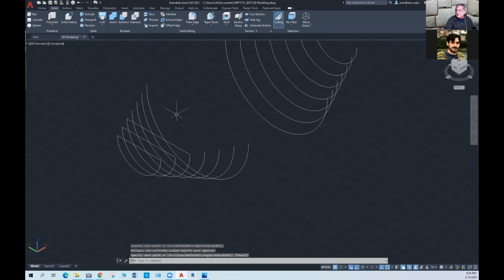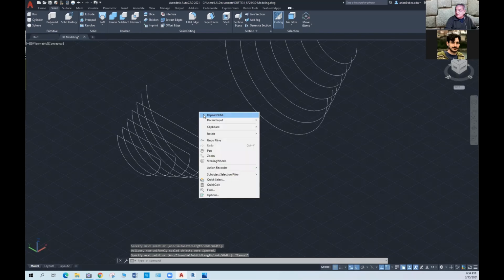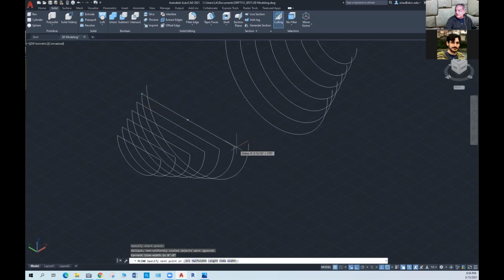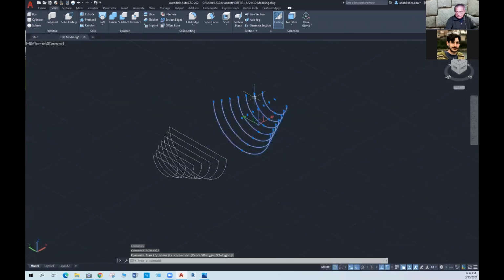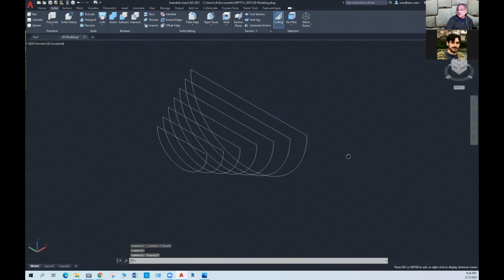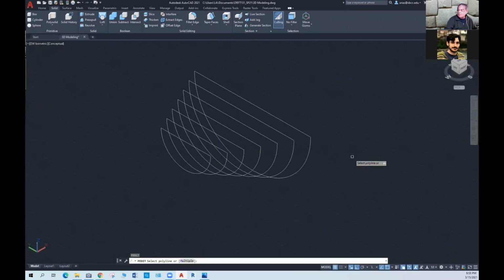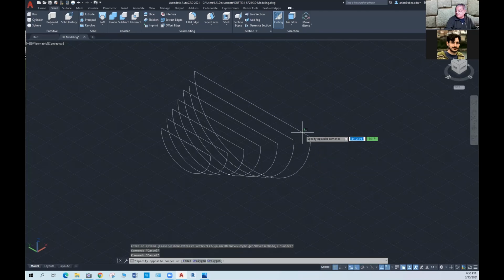And the polyline is going to be done on all the objects here. Then we'll try to see if we can, this is an interesting test, if we can actually join these as one object, PE, join, enter, okay?